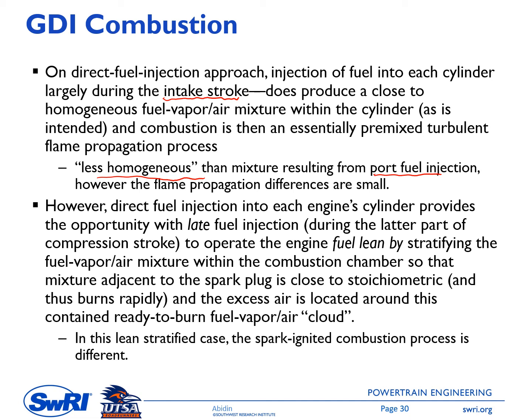And going back to the stratified mixture, overall the mixture condition will be lean. This is good from the thermal efficiency perspective because we will have less wall heat transfer and a higher gamma, and thus increased engine efficiency.